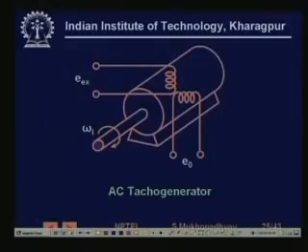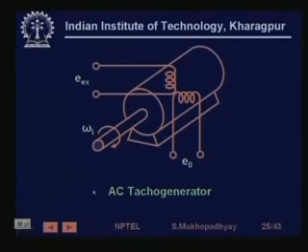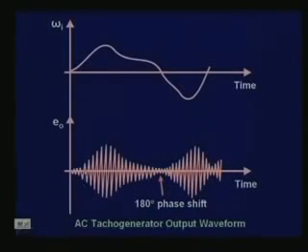The basic principle is the same: you have to change the magnetic field linkage with a coil. You create some excitation either from a permanent magnet or from some voltage source, which can be AC or DC, and as you change this excitation, the flux linked with the coil will change and there will be an induced EMF.